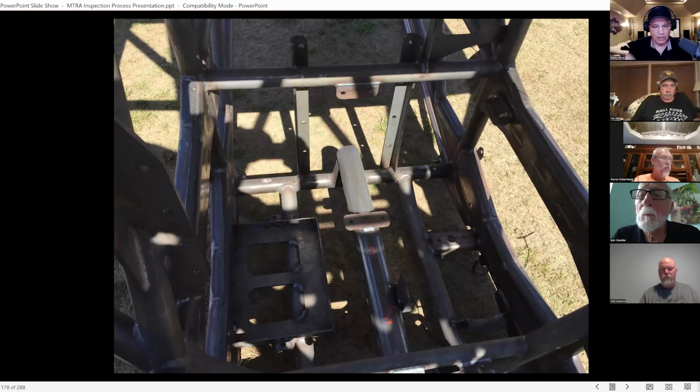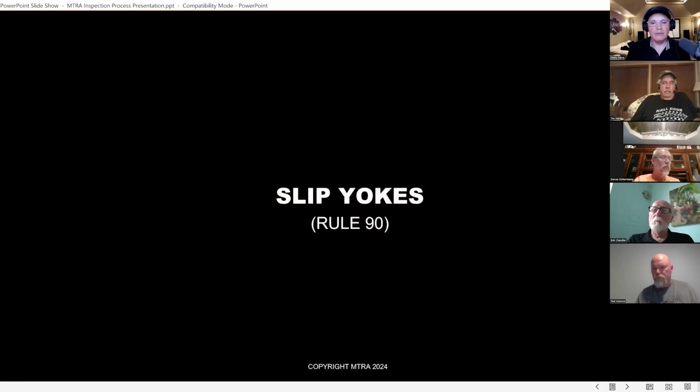It's almost like an axle shaft that uses a coupler at the transfer case, and then it goes to a solid billet block with a bearing, and then it just has a yoke there. So they're simplified. There's less pieces. Those are favorable, but you may see cases where older trucks, Gen 3 trucks might have an actual jack shaft, like a long wheelbase straight truck, because you can only make those spline shafts so long. In some cases, a real long wheelbase truck might have an actual jack shaft.